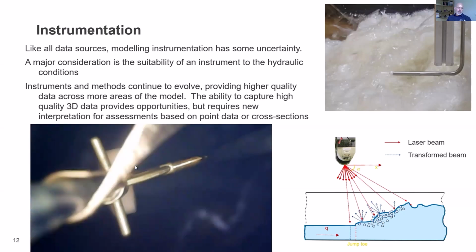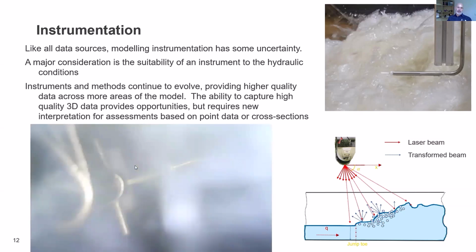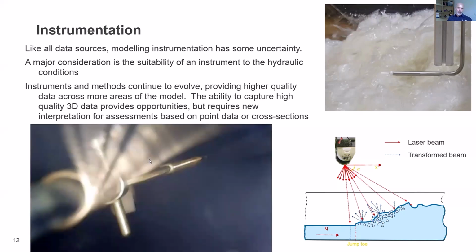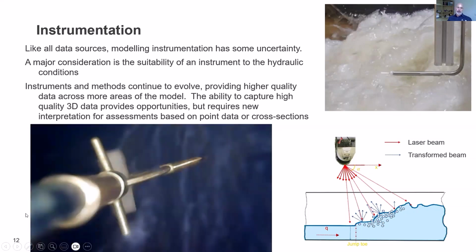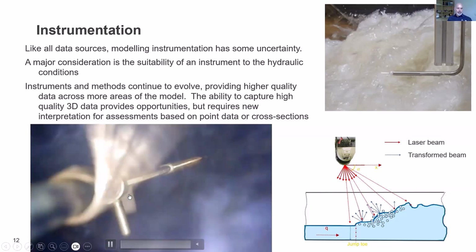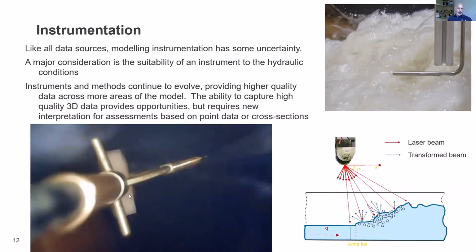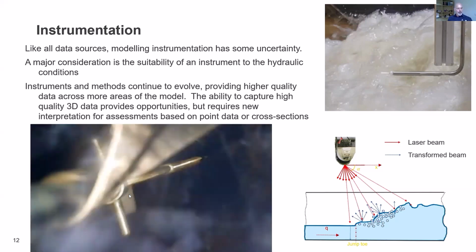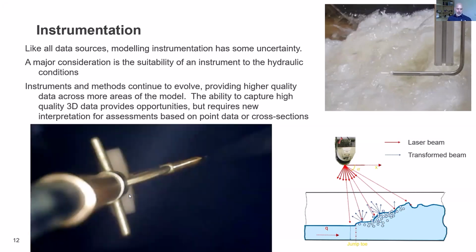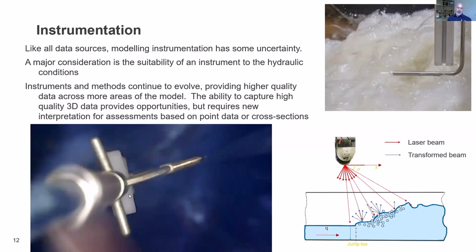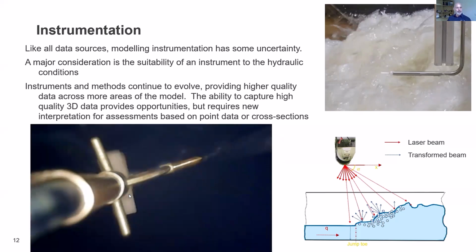In the past, we've seen people using these, and this here is underneath highly aerated flows, so you can't actually see what's happening at the bed. This instrument will give us a result, but you can see with this flow vane here that it's swinging back and forth wildly. So we can clearly see that the flow conditions are so complex here that we can't take a measurement point. It's just not realistic. It is valuable information, though. We know something about what's going on in those flows. We know it's highly turbulent and switching back and forth. This is located just downstream of an end sill, so in a place of back roller recirculation.